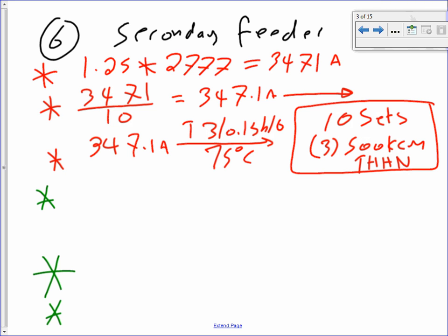When you size, guys, try to hover around 400. So if I give you 4,000 amps and you need to size them, try to divide the 4,000 by 400 or 350, something like this. That will give you a 500 or 600 kcmil conductor to pull. When you start paralleling, if your conductor is larger than 400 amps, go around 350 to 400. Anything larger than 400, definitely start paralleling.